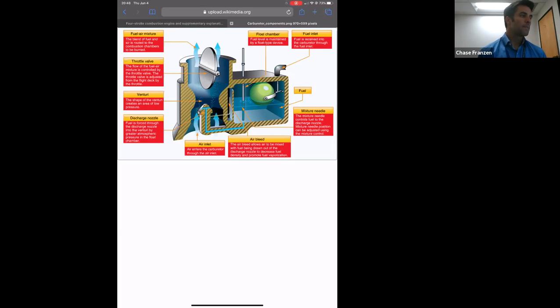And where do we draw that from the primer? Is it from the wings? Where do we suck from? The primer is sucking from the fuel reservoir, the thing that's on the screen. Okay. It's not from the gascolator? I don't think so. Is it? What is a gascolator? Yes, in Cessna, I don't know. The gascolator is the lowest point. It's a little tiny sump inside of the engine.